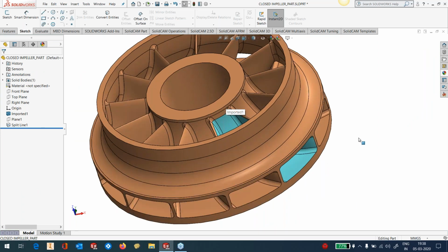This is the first part. The most difficult part in this whole example is going to be to determine the tilting mechanism. It's obvious that our regular tilting mechanism, like using angles, lead, lag, side, tilt, they're not going to work. You need to have a special tilting mechanism for such parts. The tilting mechanism, which is widely used in most of the 5-axis part, is tilt through curve.